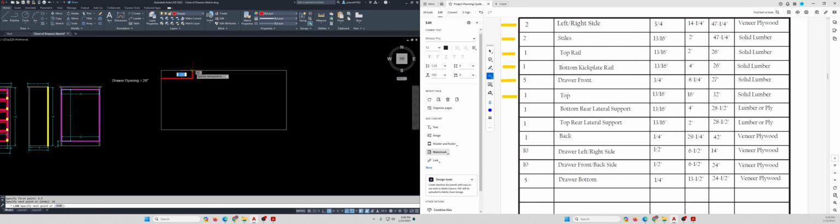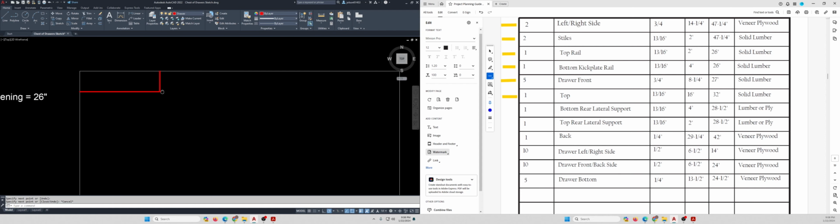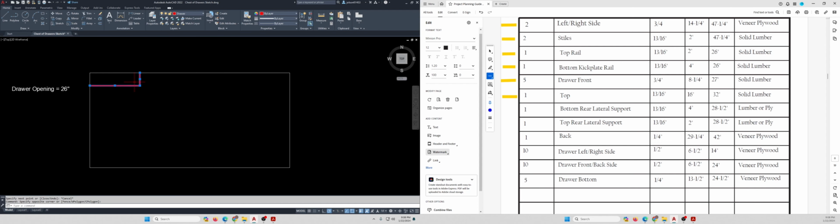And let's start with this 24-inch measurement. And this is what I was talking about in the previous video, how if I lay these out, it comes out perfectly. And the problem is we lose 1/8 of an inch by the saw blade, the kerf, and so we can't actually get 4 pieces out of that. And so we'll kind of lay this out and just see how it goes.